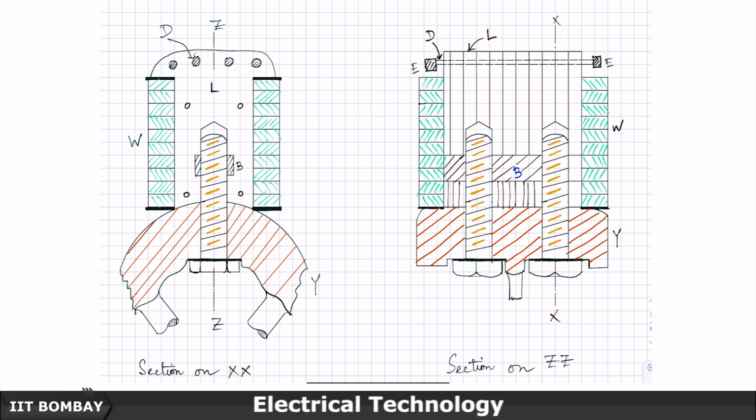If the pole is like this, there will be one bolt here and another bolt here. From here I see only one bolt, but when I see from this side, I can see two bolts which are used, and this is the riveting done to hold these laminations together. The bolt has to go around this mild steel piece which gives it strength.